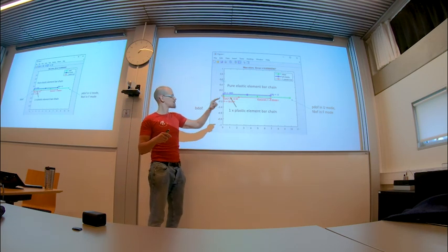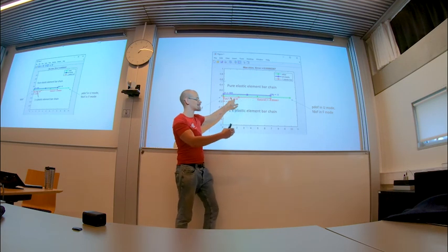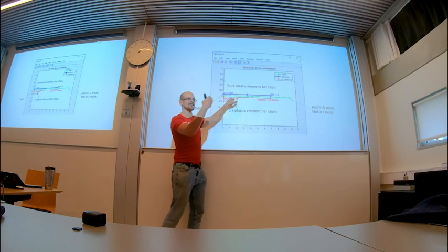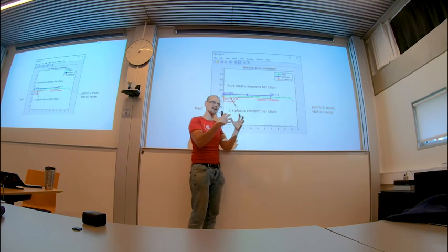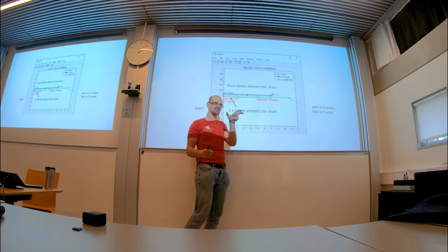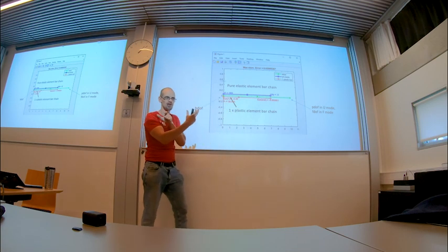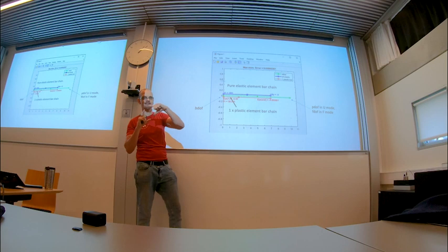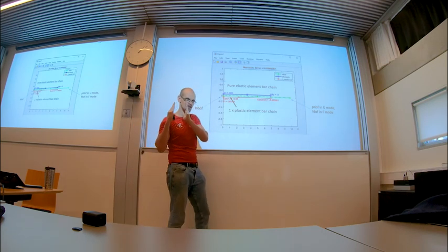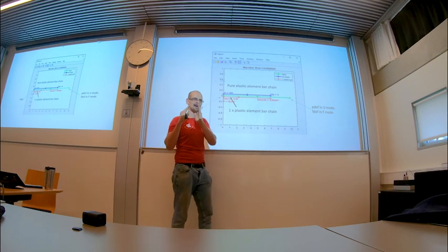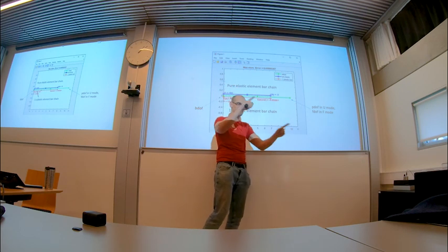And it also relies on finding the stresses inside each element in series, one after another, and then converting the stresses into a plastic strain increment and a plastic strain increment back into some kind of force. There is a method where you just take the force and forget the plastic increments completely. And then all of a sudden you don't need to go through local element by element micromatrix inversions. It makes it possible to put everything into one continuous parallel vector math format, where you just flip a vector in, flip a vector in, flip a vector in, two vectors together in a matrix.